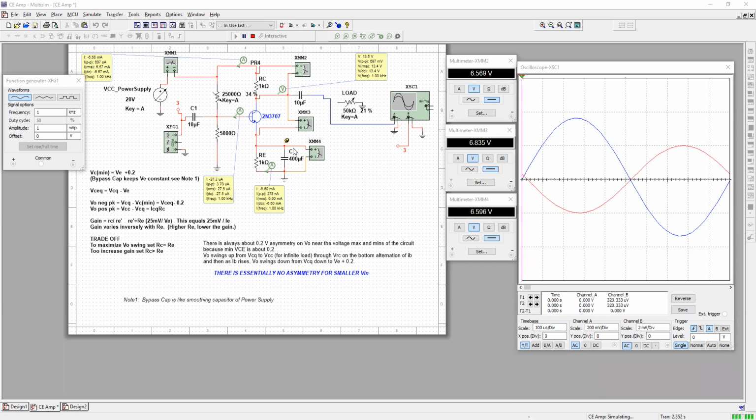Now, of course, it depended on the time constant, RC, that determined just how long you could keep that discharge flowing before you reached a lower level that was noticeable in the circuit. So the larger your capacitor, the better the smoothing out effect, the longer that time constant.